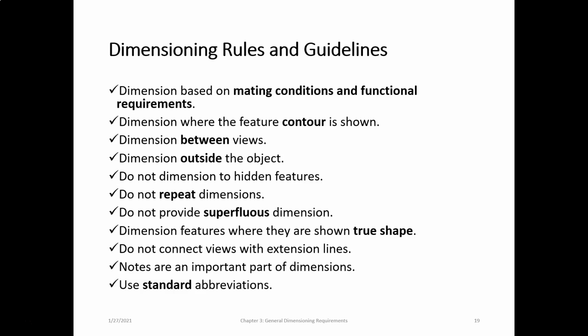Dimension outside of the object. Do not put dimensions on the inside of the object. Do not dimension to hidden features. That's a big no-no. Do not repeat dimensions between views or within the same view. Do not provide superfluous dimensions. That is, dimensions also known as double dimensioning.